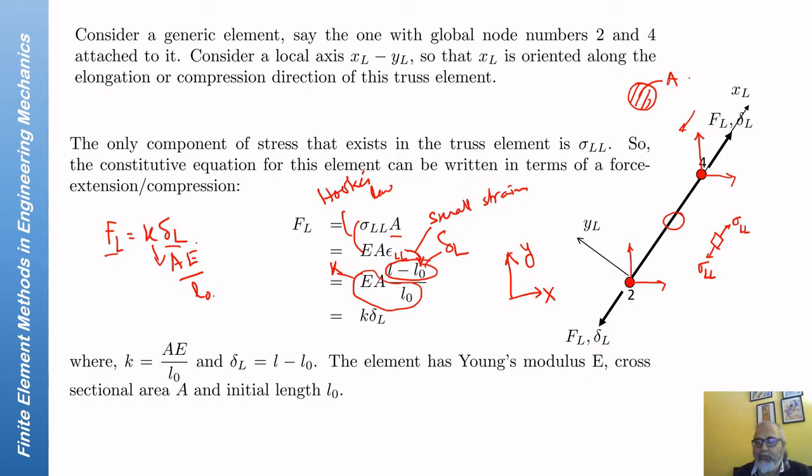We'll later do a beam element, which will also be a structural element, because there also we will deal with moments, displacements, rotations, and forces. In a solid element, on the other hand, which we will do much later, we'll deal with stresses and strains rather than forces, moments, and displacements and rotations. So in structural elements, typically we deal with forces, moments, displacements, rotations.